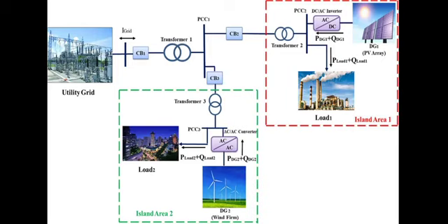Impedance-based methods. These methods analyze changes in the impedance characteristics of the power system. During an islanding event, the impedance may differ from the usual grid-connected values. Techniques like positive feedback impedance and reactive power voltage relays fall under this category.